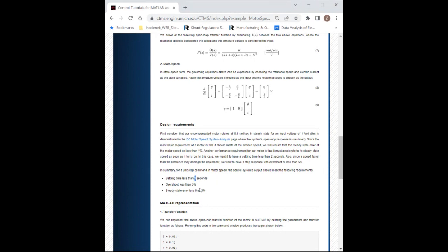It's important. Overshoot. What's overshoot? You will remember. For example, your reference speed is 500, your maximum transient speed is 600, so your overshoot is nearly 20%. I am waiting from you a maximum overshoot of 5%. What's the 5? For example, reference speed 500. Your maximum transient speed is 500 times 5 percent over, 525.